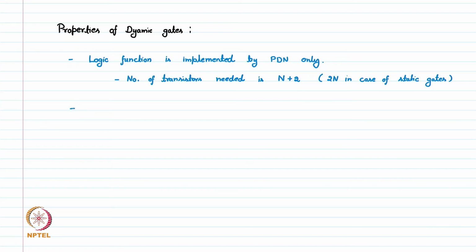The next point we can notice here is we still have full output swing. It means our noise margins are still very good. Still we have ratio-less design. The sizing of the device does not affect the logic level in a steady state.